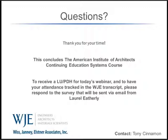ASTM C1036 has a whole section related to acceptance of glass. Now, it's acceptance, or visual acceptance, of new glass. There isn't a standard for viewing or determining condition of in-service glass like this, and that's one of the things that we're still kind of wrestling with. So, from a strength standpoint, what we saw here was that the strength wasn't really diminished. I think there probably still would have been some that would have been replaced from an aesthetic point of view, if they had too much surface damage, too many scratches.